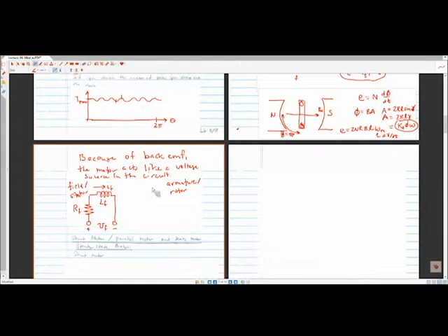we have a pretty similar looking circuit. Again, we have terminals. This would be whatever you're actually connecting your voltage source to. This is again a coil, right? So it's going to have an inductance and a resistance associated with it, given by RA and LA, respectively. And then the last thing, because this thing is turning and moving through a magnetic field, it's going to have a back EMF associated with it.